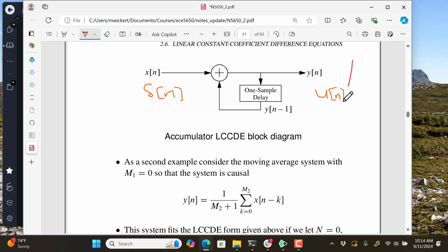Okay, that makes sense. And remember again that the impulse response definition assumes zero initial conditions. So when we start this input-output experiment out, that one sample delay register will be set equal to 0. So we will get a delta back to a step. We noticed over a week ago that a delta and a step are related to each other through an accumulation operation. And a backwards difference goes from the step back to the delta.